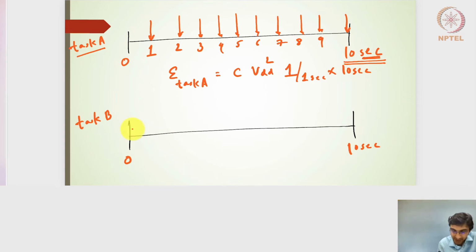So if I pick the intervals 2, 3, and then 4, 5, and then 6, 7, 8, and 9, and this is my 10 seconds. Although it is not divided linearly, what I'm saying is that in each of these intervals of 1 second, the switching we require is only 6 switchings, so it can delay its switching, or rather it can have a reduced rate.